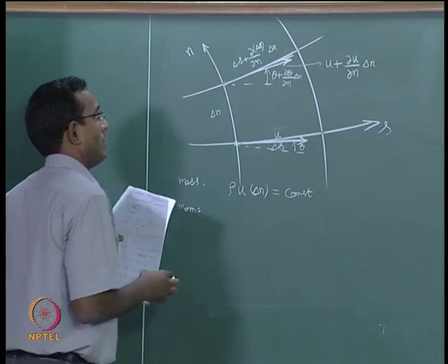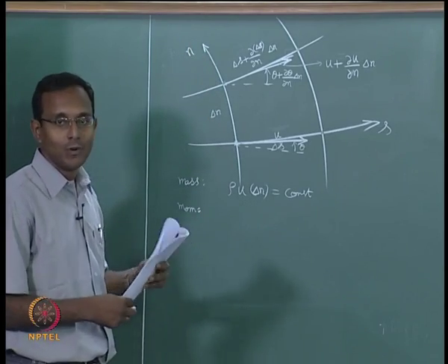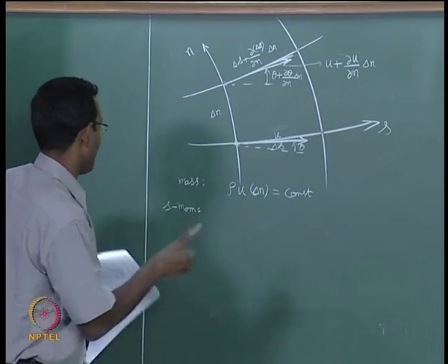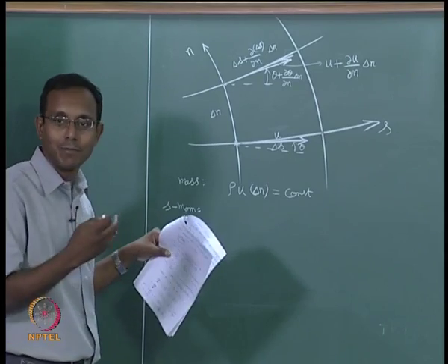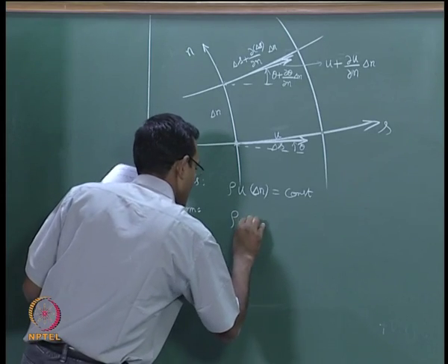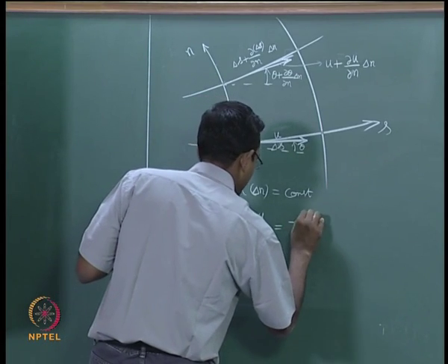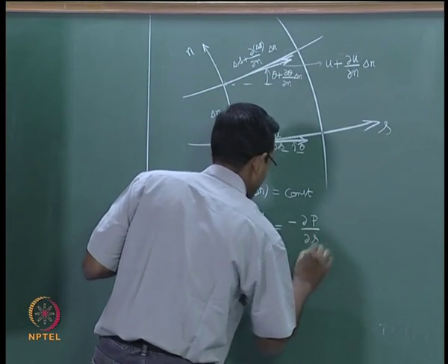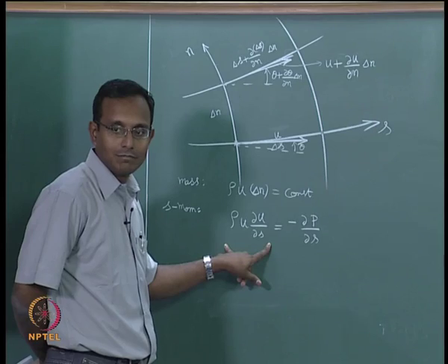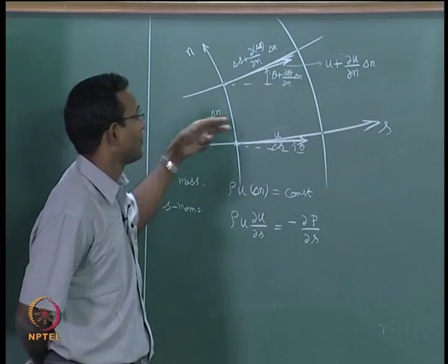Similarly, momentum. Now you have to be a little more careful, forces can act along this n direction also. So now I have to think about s momentum first, only along the s direction, the s momentum equation, like we had x momentum and y momentum, right. So here it is the s momentum equation. Now it can be written as rho u ∂u/∂s equal to minus ∂p/∂s. If you look at this, this is the acceleration of your fluid element, inertial forces here, and that has to be compensated by the pressure force from here to here.